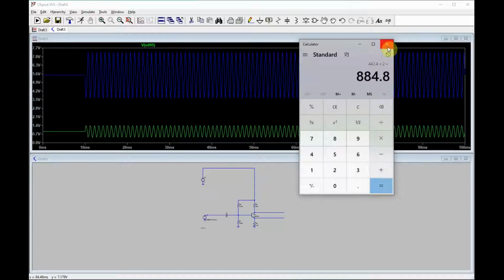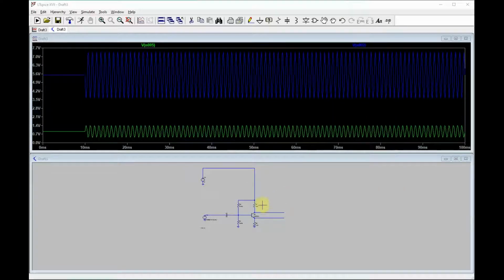It's kind of 0.8. So this is kind of low. I think I probably should have given it more headroom. But on the other hand, we're not going to exceed it. I've scoped the signal actually and found that this was adequate, because of the loss in the amplifier.